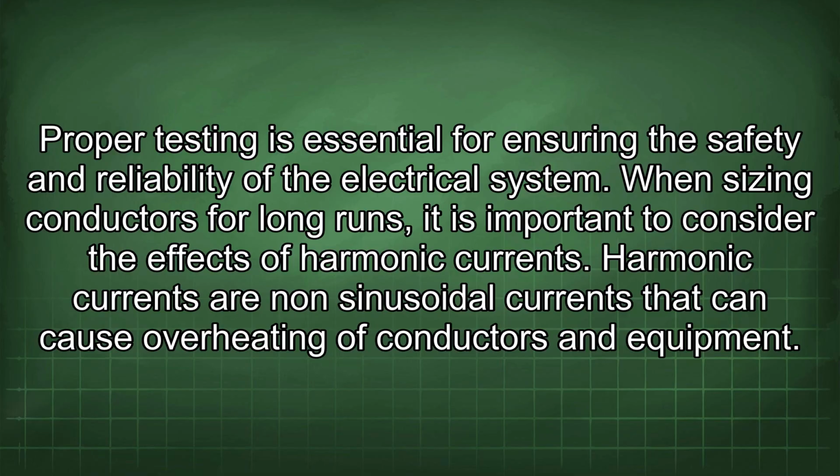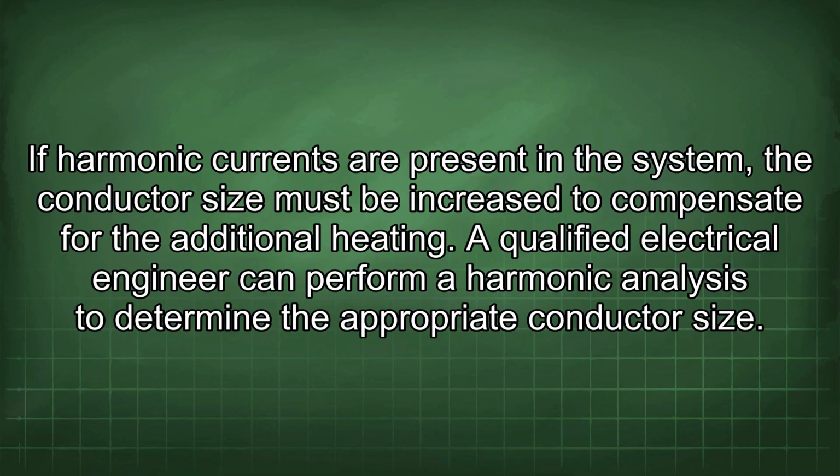When sizing conductors for long runs, it is important to consider the effects of harmonic currents. Harmonic currents are non-sinusoidal currents that can cause overheating of conductors and equipment. If harmonic currents are present in the system, the conductor size must be increased to compensate for the additional heating. A qualified electrical engineer can perform a harmonic analysis to determine the appropriate conductor size.